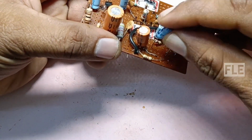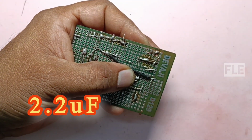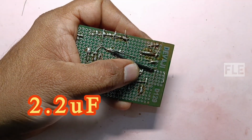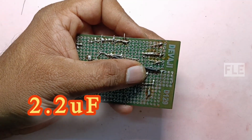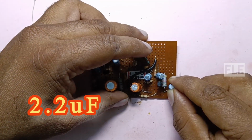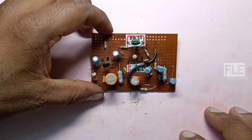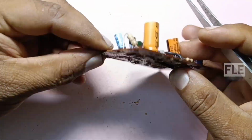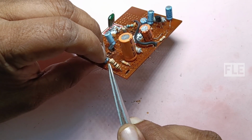Connect the 2.2 microfarad output capacitor. The positive terminal of the 2.2 microfarad is connected to the collector terminal of the second C1815 transistor. The audio output is from the collector terminal using the 2.2 microfarad capacitor.